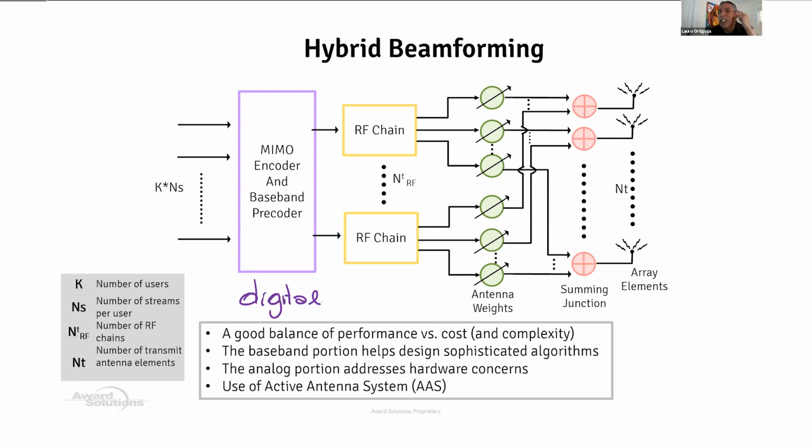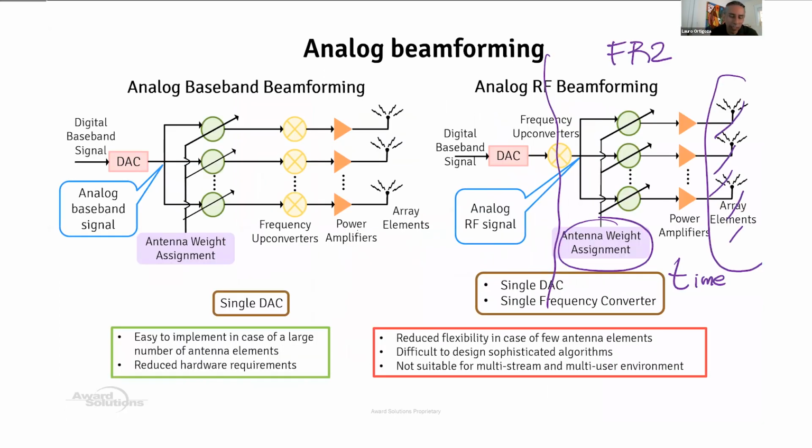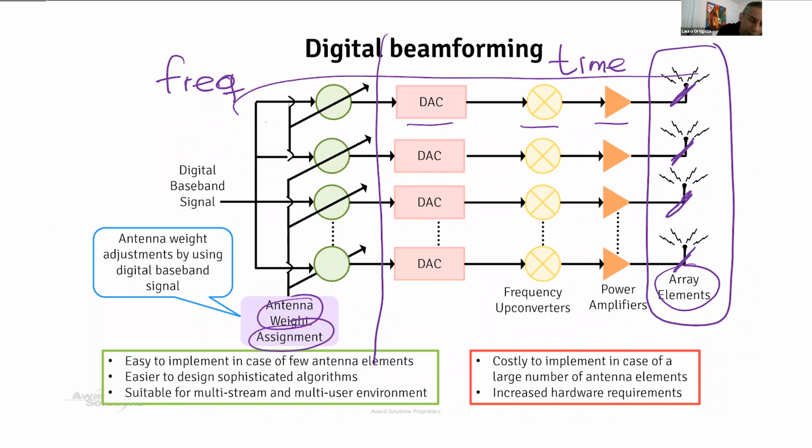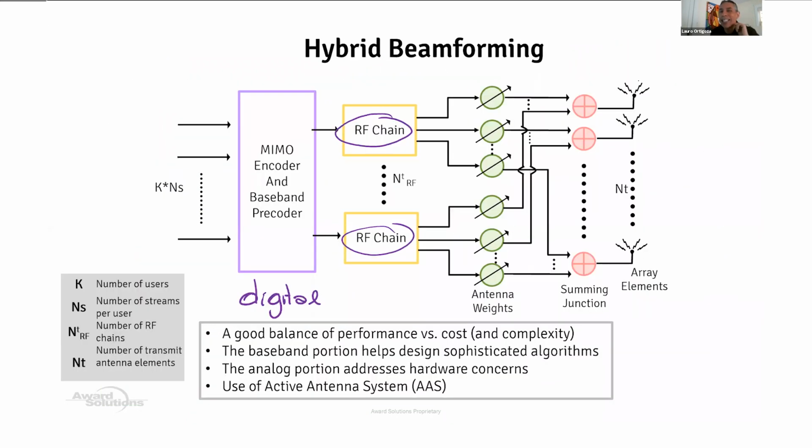Okay, so 64 by 64 massive MIMO means that you have 64 subarrays, right? If your vendor supports sending one layer per beam, meaning that you can have 64 layers, then you can do 64 by 64. Currently, the maximum is 8 by 8.